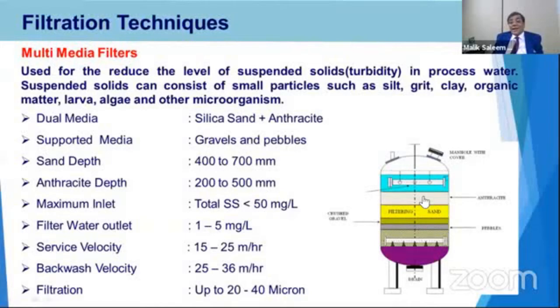Anthracite is a bit bigger size media, and we place a bed of anthracite on top of the sand so that we can increase the run time of the sand filter.